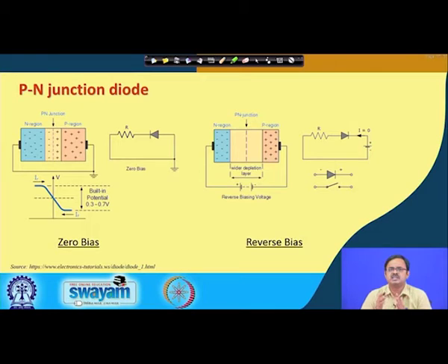It's a region that is devoid of any free charge carriers, whether it's electrons or holes, because the hole and the electron recombine. But however, as they recombine, what happens? If you look to the right, you have a p region which has a lot of positive charge carriers. On the left, you have the n region with a lot of negative charge carriers. In the middle, we have what is known as the depletion region.